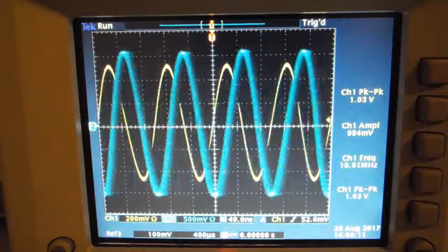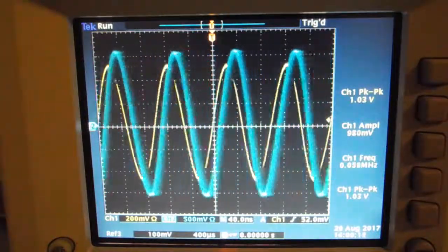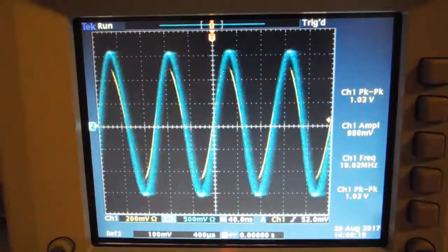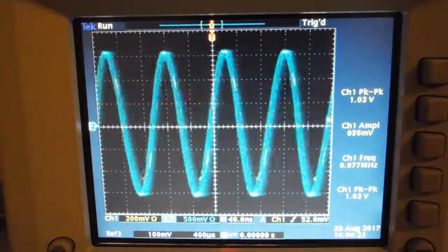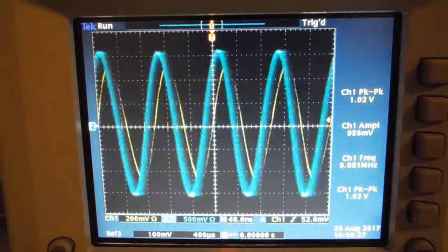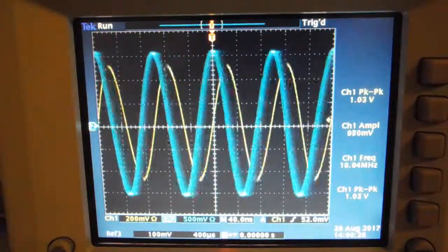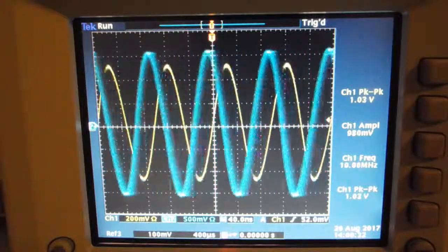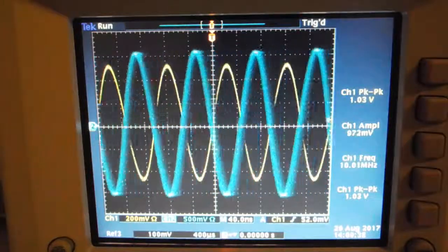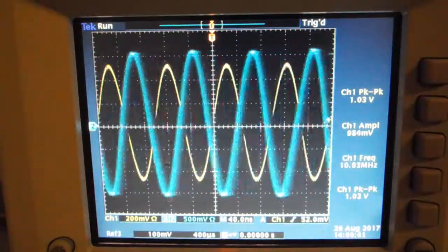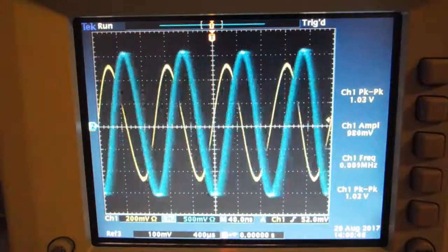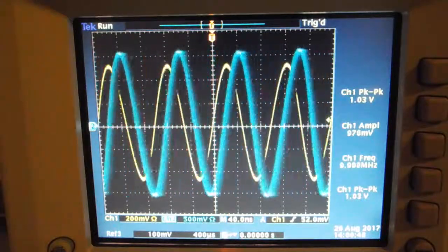This oscilloscope image shows two 10 MHz sine wave signals coming from 2 separate devices running 2 separate master oscillators. The blue waveform is from the Novatech Instruments Model 2975AR signal generator, where the triggered yellow waveform is from the Novatech Instruments Model 409B signal generator. There is inherent drift between the 2 signals due to the fact that they are running on 2 separate master oscillators, which is an example of non-phase synchronous operation. We will do our best to try to synchronize these 2 waveforms.